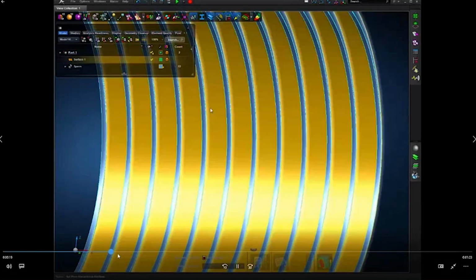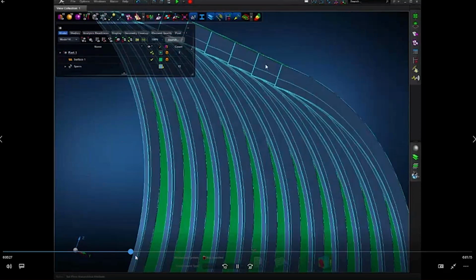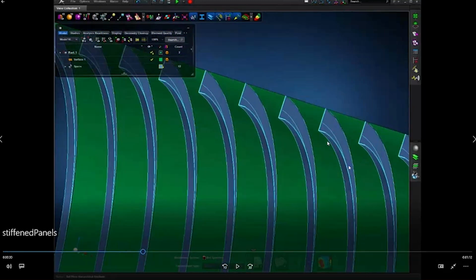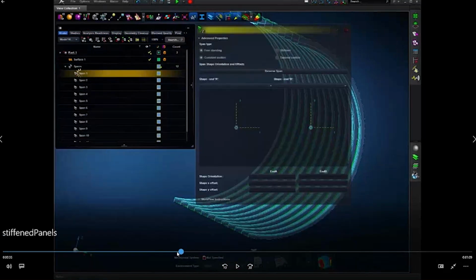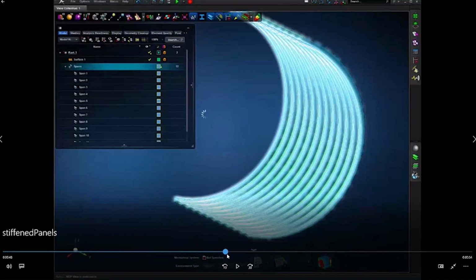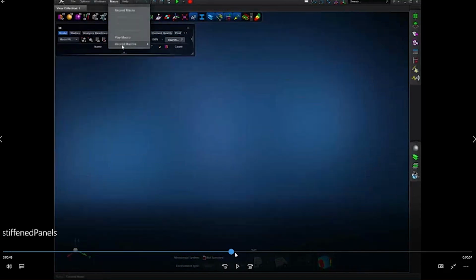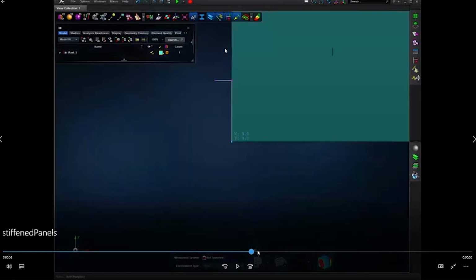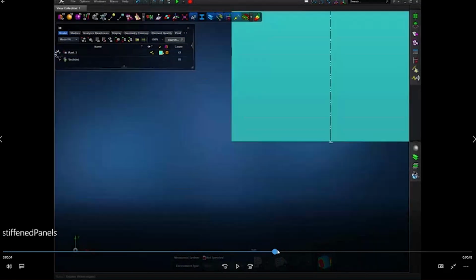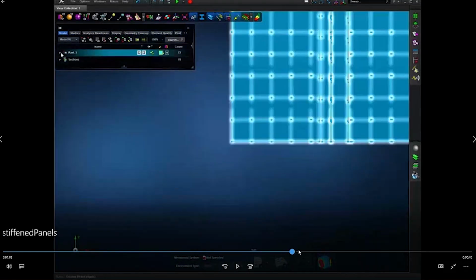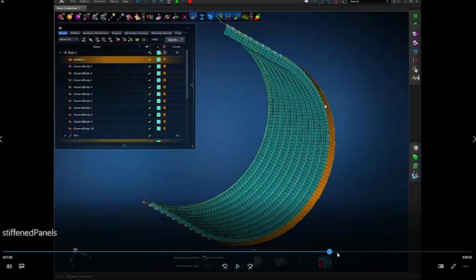Maybe I can fast forward to see. Basically, that's what it is. The script created the stiffened panel. In this case, it is the L-shaped sections, right? And now the second script here is to create the 1D profile, the built-up panels. So basically, in this case, it created the 1D profile beams.